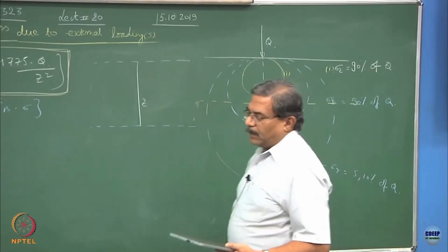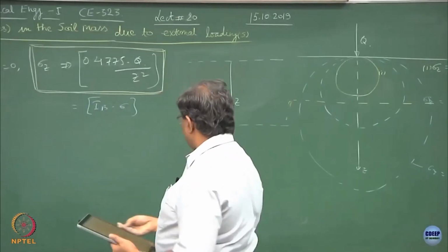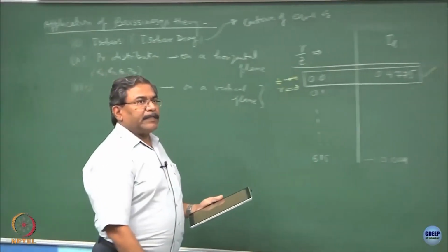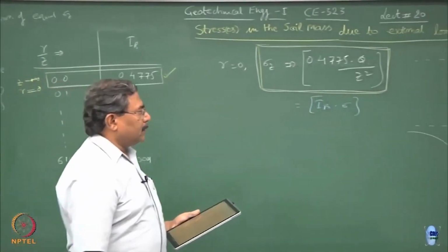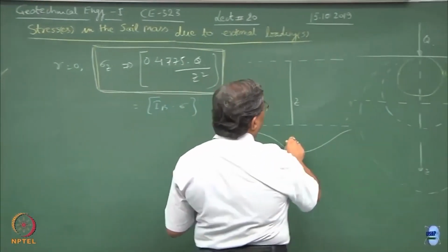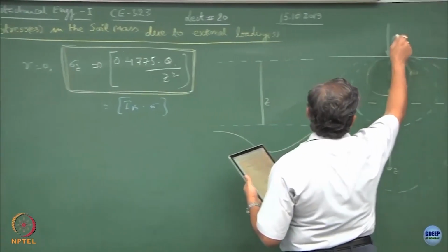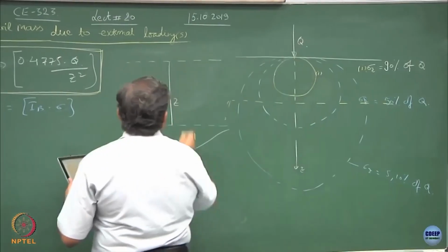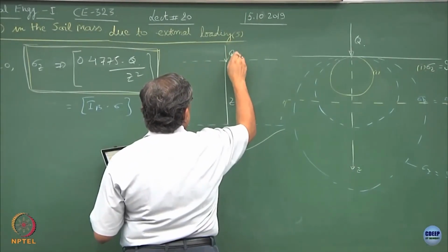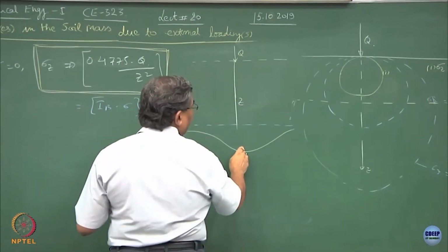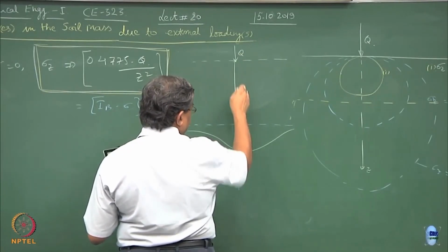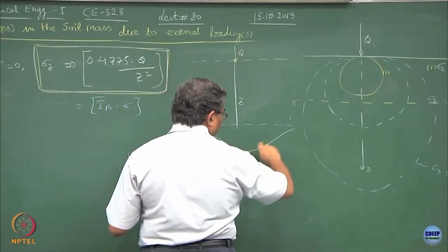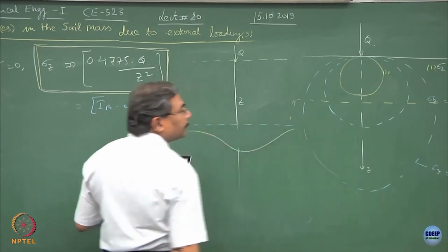this is the same plane as what I am showing over here. So, the pressure distribution would be like this. Why the rutting takes place in pavements, this is the answer. Excessive loading, the tire pressure from the vehicles, creates the maximum intensity of the pressure at a certain distance Z, just below the point of application, and beyond which it fades out.